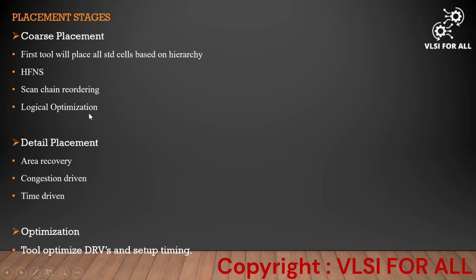The next step is logical optimization. The tool performs the optimization based on the logic we have in this stage, which means it works on Boolean algebra expressions. With that, it will reduce the logic further if possible, like taking some K-maps to reduce that logic. So it will optimize the gate level netlist.